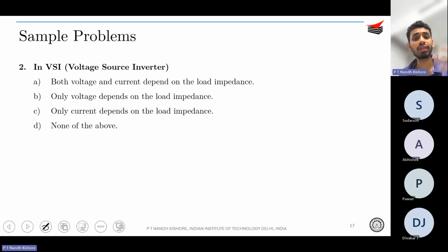Only then you qualify the battery as a voltage source. So that means that the battery voltage is independent of your load. It is maintaining 5 volt irrespective of whatever be the load, whether it's open circuit or 5K or 20K or 100 ohm or whatever it is.